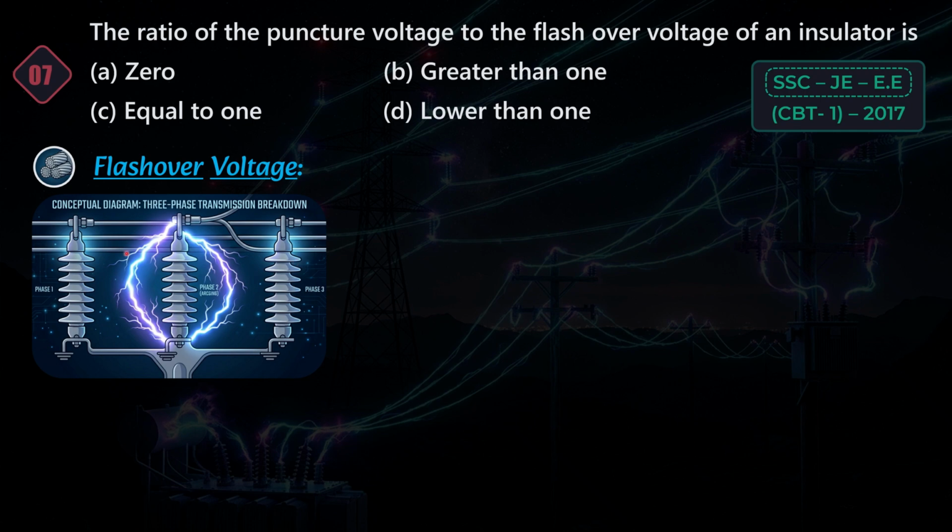As you can see in the image, electrical arc gets developed when voltage increases beyond the predetermined value. And this arc jumps through the air, traveling around the surface of the insulator to reach the grounded tower. This is called flashover, and the voltage at which this happens is called flashover voltage. However, flashover causes a temporary short circuit, but the physical body of the insulator remains intact. Now let us consider what is puncture voltage.